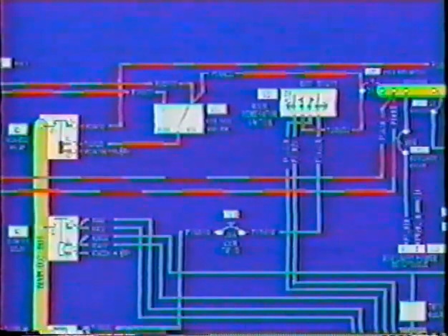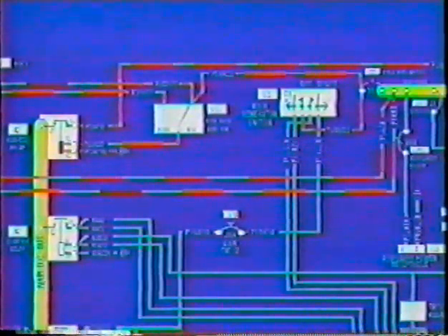Follow the wire leaving that bus through the generator and bus reset circuit breaker. Continue the trace to the non-essential bus switch. With the switch placed in the manual position, controlling power is placed on the non-essential bus relay at X1. The process of transferring power is then duplicated as with operations in the normal mode. This is why non-essential bus operation is possible either in the normal or manual position.